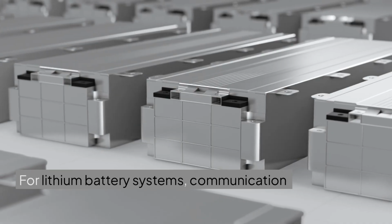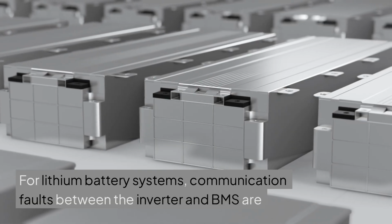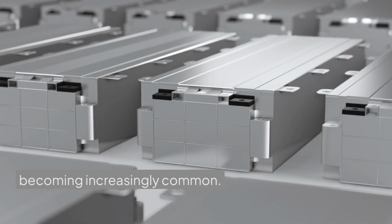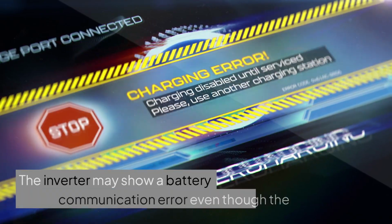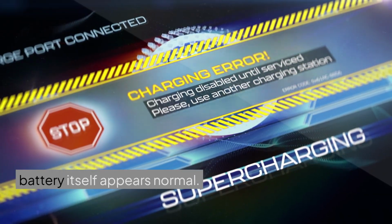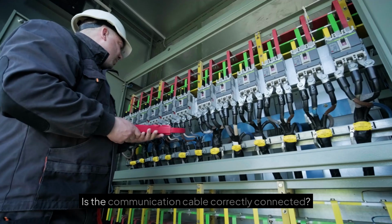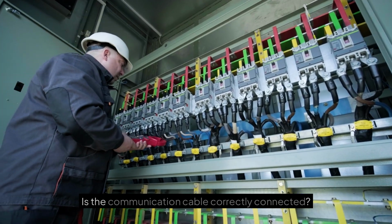8. Communication or BMS fault. For lithium battery systems, communication faults between the inverter and BMS are becoming increasingly common. The inverter may show a battery communication error even though the battery itself appears normal. Check: Is the communication cable correctly connected?